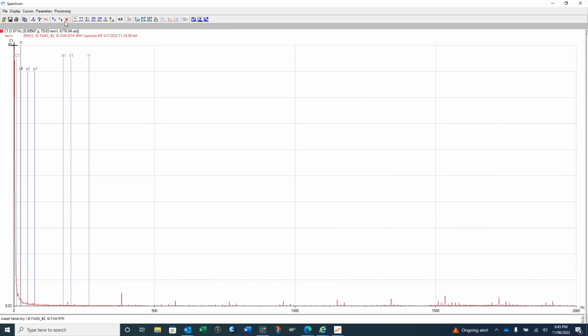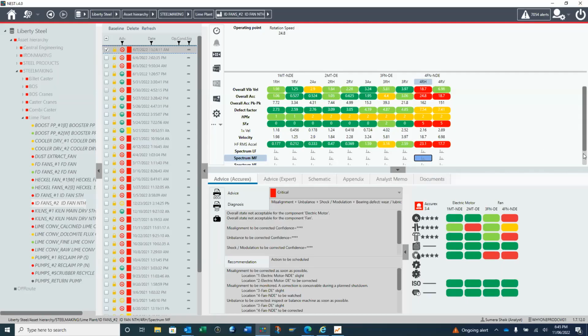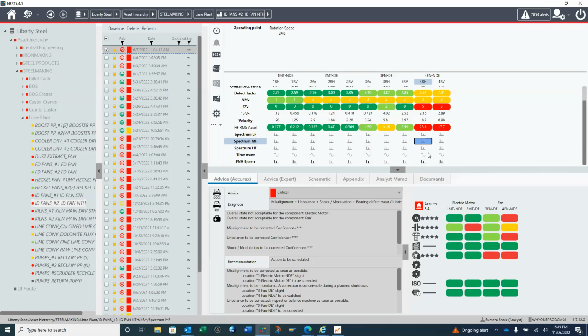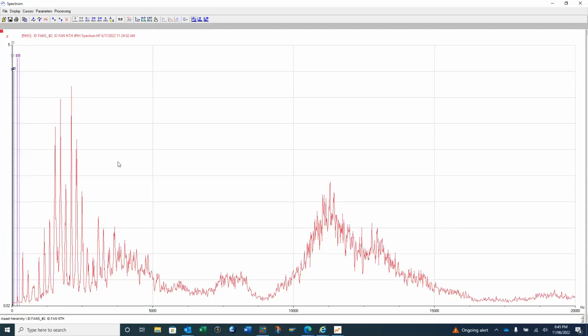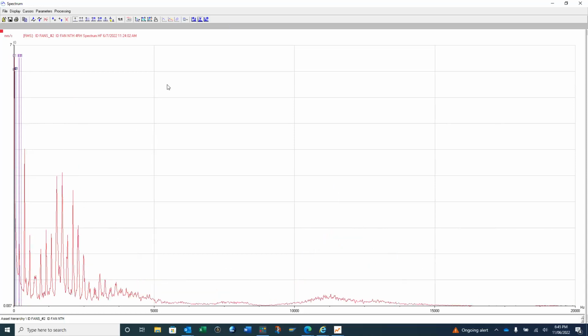I think there might be some issue with this. I have to go and check again. There's a sound, maybe from alpha or bravo. Sometimes there's sound in the surroundings, and the accelerometer picks up that sound. So that's not true vibration, the 1.25 hertz.